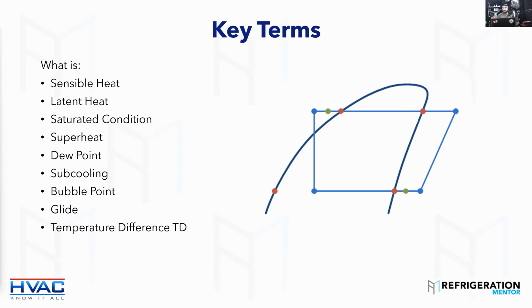High side as well, 100%, Brennan. High side as well. You need to understand. So my quick example, I got one here, is you have a 25 degree Fahrenheit coil or -4 Celsius, and the box temperature is 35 degrees Fahrenheit or 2 Celsius, and the TD would be 10 degrees Fahrenheit. So the coil's 25, the box is 35, so that return air, and you get 10 degrees. And I actually have it here in my notes. Delta T is air in versus air out.